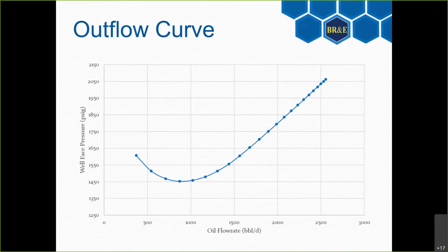That's what we see in almost all cases, no matter what sort of piping you're talking about. The more you put in it, the more pressure drop you're going to get. And knowing that the outlet pressure is static, the only way that pressure drop can be reflected is by having a higher delivery pressure or higher injection pressure from the well face. There is a slight section where that curve does double back on itself, for reasons with the fluid properties. Sometimes you will hear the outflow curve called the J curve. It is somewhat common to see it have that uptick. Not always, but sometimes it does.